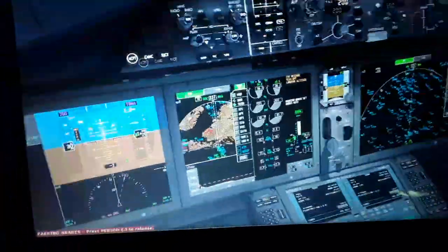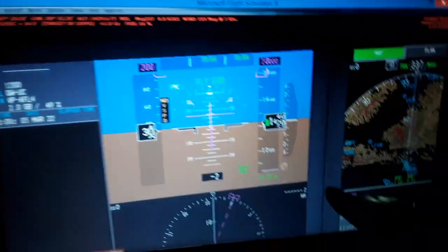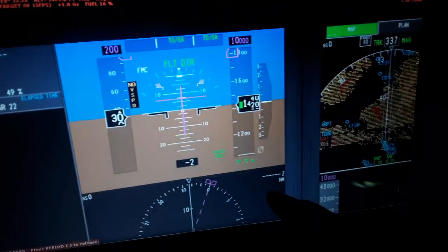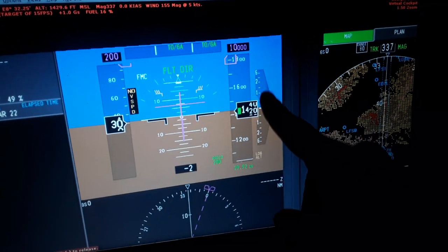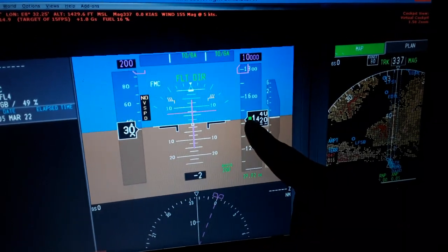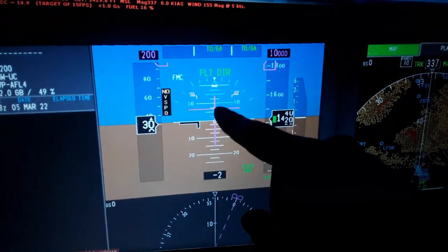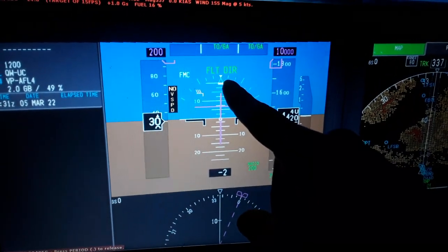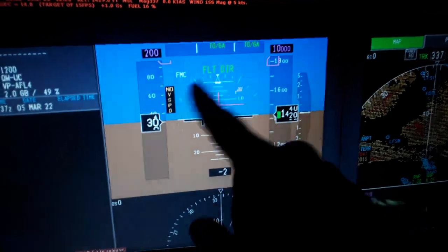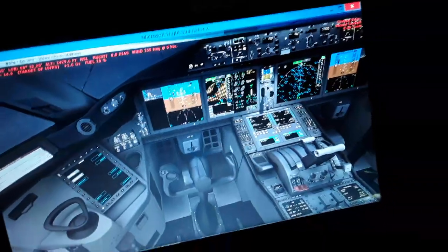As you can see here, the primary flight display, you can see the airspeed indicated. Over here, the airspeed selected from the autopilot flight director system panel, the barometric altitude above the sea level, the target altitude selected from the autopilot flight director system panel, the vertical rate of climb and descent of the aircraft in tens, hundreds and thousands of feet per minute, the steepness of the trigonometric angles in degrees you can set from the flight management. From the autopilot flight director system panel, the pitch ladder in degrees 2.5, 5, 7.5, 10, 12.5, 15, 17.5, 20 degrees for pitch up or pitch down, and the bank angle in degrees, the flight mode annunciator with the autopilot and the auto throttle, later vertical navigation modes.